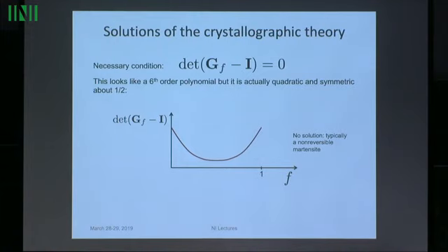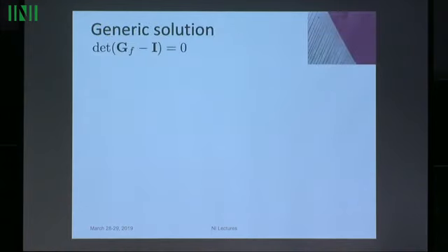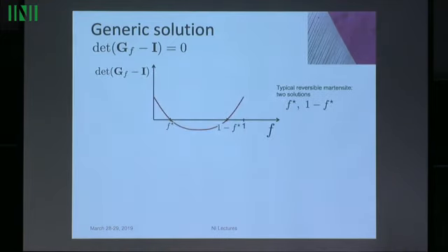If you take measured lattice parameters of some martensite which is not reversible, for example, a martensite in steel, take the measured lattice parameters and stick them in and calculate this quadratic function, it may well look like this. So not every martensitic material has austenite-martensite interfaces. Okay, so a typical non-reversible martensite may well not have a root at all. This material, of course, has a root, as you can see.